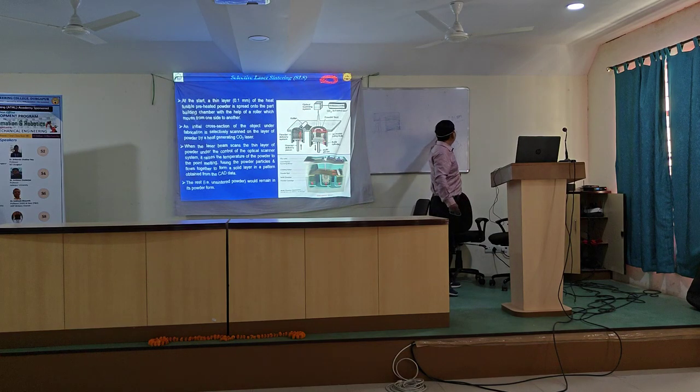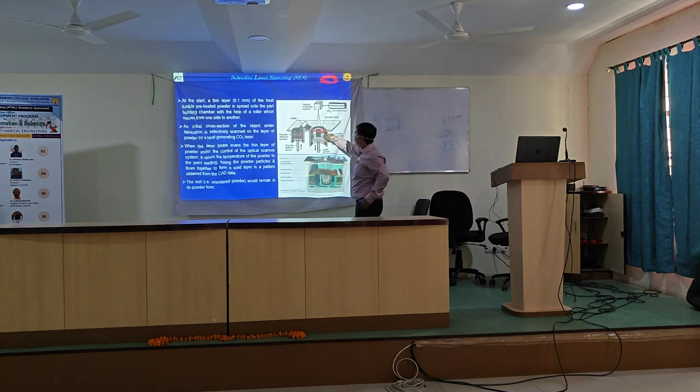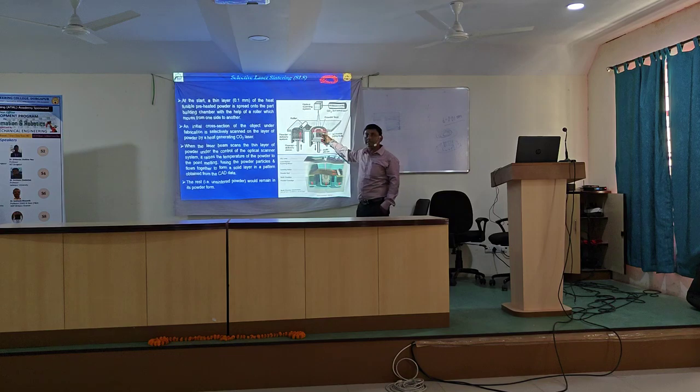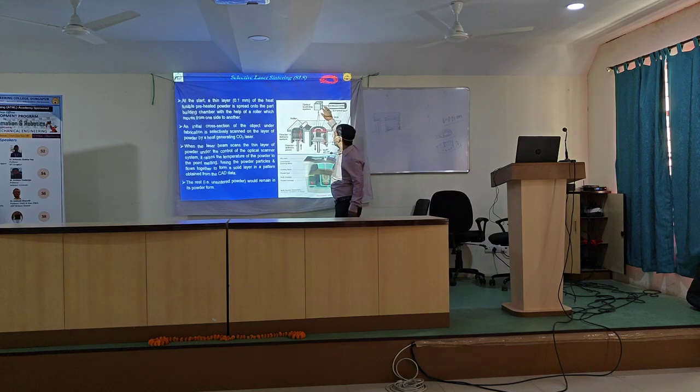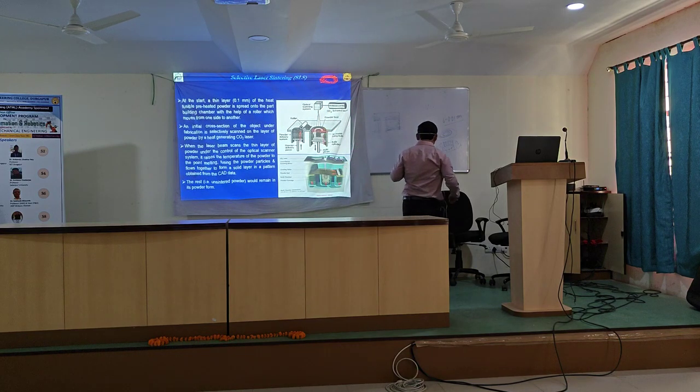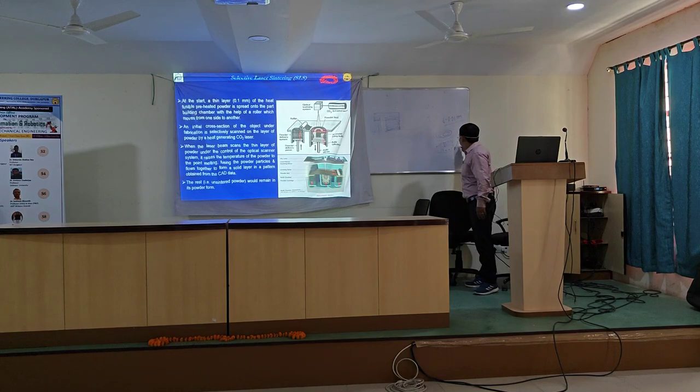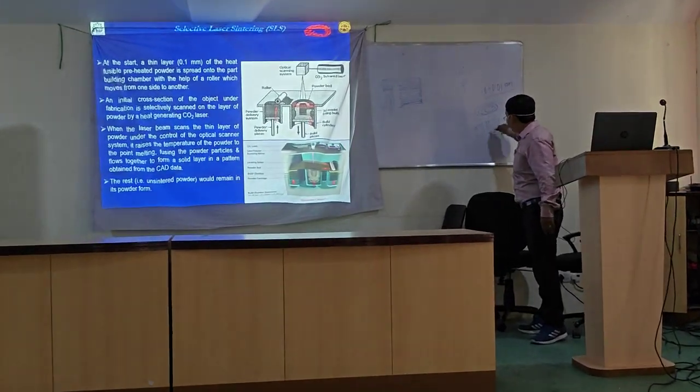During your slicing, if you put a layer thickness of 0.01 millimeter, then you set that particular thickness. That amount of powder you have to heap up through the movement of the piston and spread over. Now, according to the processing information, same as SLA, from the laser source through the optical system, the laser will trace the cross section. The cross section is this one. Again, the same as in SLA, the laser will trace the outer boundary, the inner boundary, and inside also the laser is tracing.